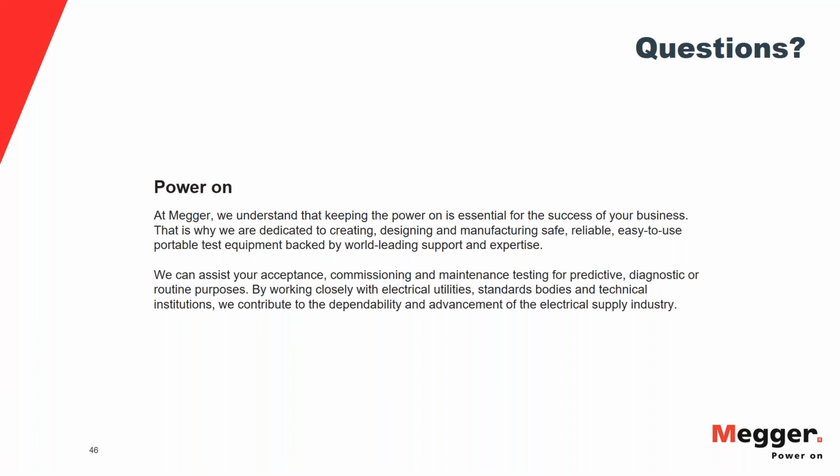All right, next question. Does the fault current always lag voltage? If so, why? Mohit, can you take that one? Yes, I can take that one. It is not necessary that the fault current will lag the voltage. When you have high capacitance on your transmission line, meaning that your capacitive reactance is higher than the inductive reactance, you can have fault current leading the voltage. So there are some cases where you can also have faults where the current is leading the voltage.